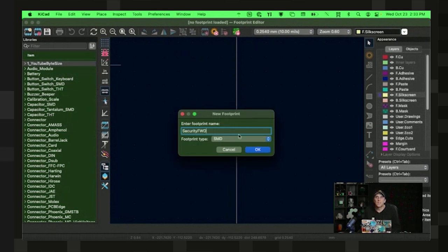And this is also where we can decide whether it's an SMD or through hole pad design. So in this case, it really matters. The difference between the two is that SMD, or surface mount design, is something that is soldered flat. It is going to be much more manufacturable by machines. You'll find that there are a lot of modules done this way in order to conserve space and make it easy to mass produce these.